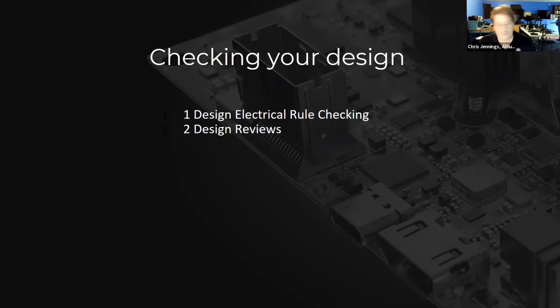I've had an engineer say, I know that part's on the approved company list, but we never use it because every now and then you just can't get it. It's just not available. There's a weird supply issue. So it's not written down anywhere. Nobody knows about it, but everybody avoids that part. And that's really valuable because it means your design can be built when you need it built, and as often as you need it rebuilt, you can do that. So it can be frustrating to have a design review, but at the same time, it saves a lot of aggravation in the long run, and you have a higher chance of success with your design.